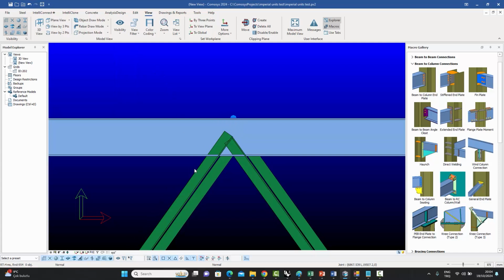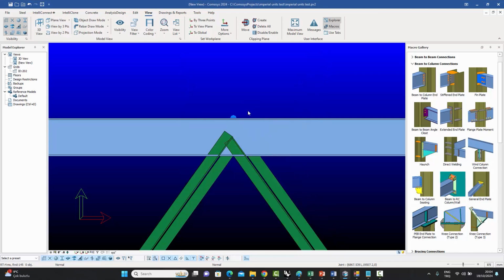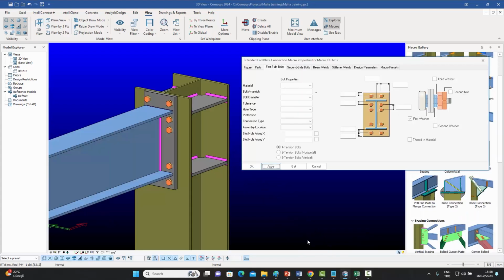If you notice, both of them are still there. The node is still there, but inside these numbers have been modified so that the working point comes to the middle of the beam. So the third handle basically allows you to do what adjusting them would have done. That's a very useful way of working now.